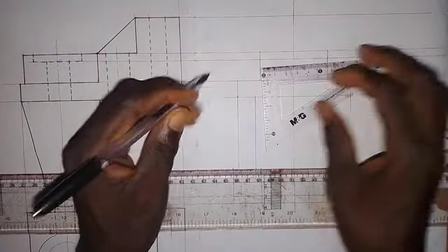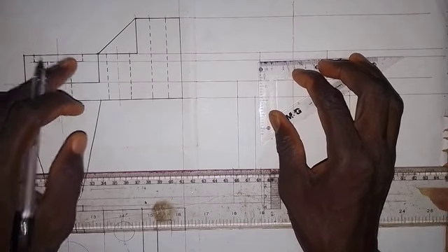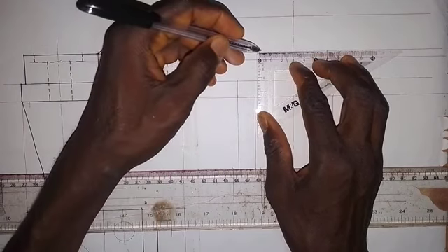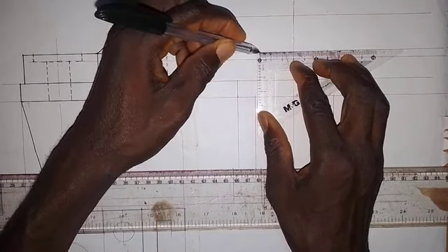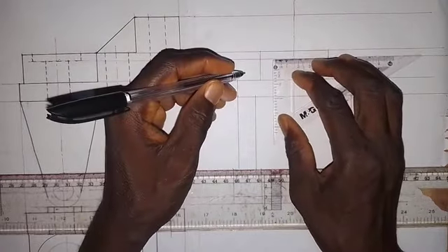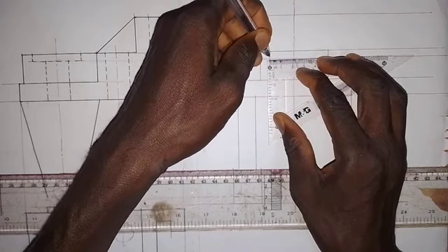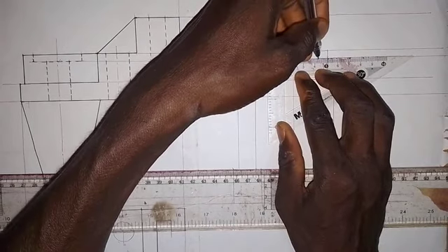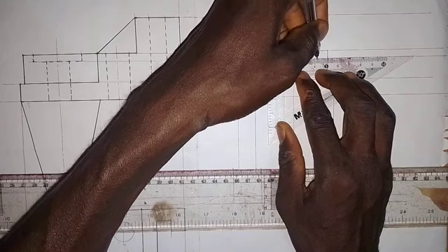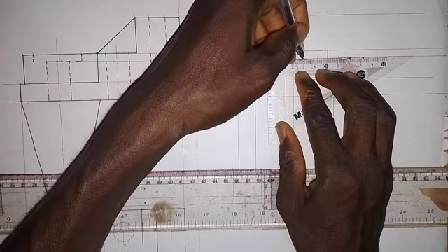So first of all, work on, and then don't forget that the depth of that is 6 millimeters, which we have already done. So we first of all make this line. This line will be a thick line, so it will be a thick line from here to here. So let's make it a thick line at once. Then we take a measurement of 21 from the center to the left side, and 21 from the center to the right side, making it 42 millimeters. So this is 42 millimeters. And also we take 10 for the small one. We also take 10 to this side.